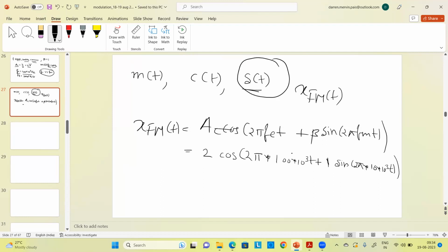Okay, now see, here we just use a general equation. So the thing that you asked me, whether it's wideband or narrowband, didn't matter here, because we use just the FM signal, irrespective of whether it is narrowband or wideband. So in the question, anytime you get confused, don't worry. Just try to use the general equation, because that is applicable for both narrowband and wideband. Am I clear? Yes.